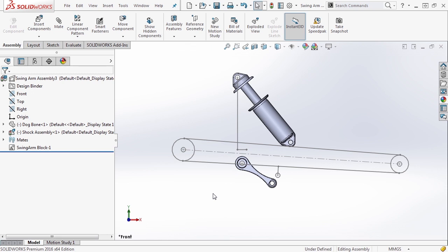Now, when you're designing parts in SOLIDWORKS, there are a few different workflows that you can handle. The shock was created using a multi-body workflow, which means both components, even though they were meant to be an assembly, even though they were meant to move, were created in a single part file, broken out into their own part files, and then brought back into an assembly. Now, that's very powerful because we can modify the original part file and it'll all trickle down out to those individual part files and back into the assembly. The benefit of that is if we modify the individual assembly or the individual part files, it doesn't go back to the original multibody file. So it's a one-way workflow.